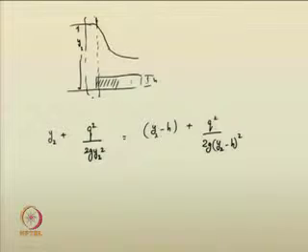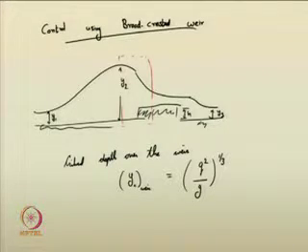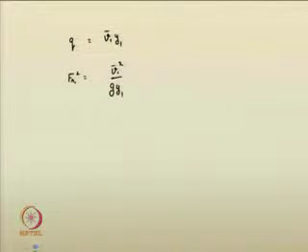So, using such specific energy equations, you can now find the relationship for q squared, that is the discharge per unit width. You can get it as 2g y2 squared into (y2 minus h). You just rearrange the terms, you will get the following relationship, right. Now, we can also see that q is nothing but the velocity at section 1, that is the pre-jump condition. So, velocity is known to you, y1 is known to you. You also know the Froude number at the pre-jump section, V1 squared by g y1 is the square of the Froude number. So, you can substitute these quantities in this particular equation, fine, and what we will get is